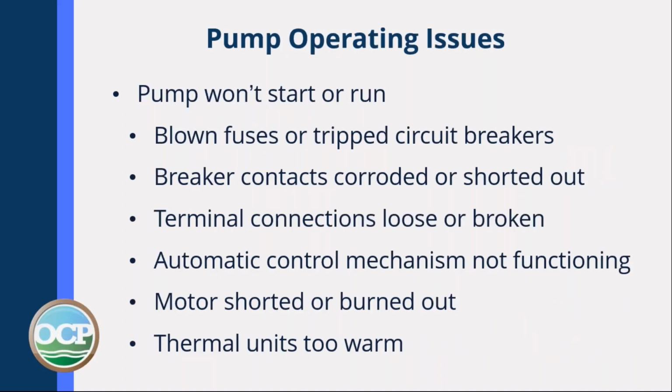Operating issues: if the pump won't start or run, check for blown fuses or tripped circuit breakers, breaker contacts that are corroded or shorted out, terminal connections that are loose or broken. Check the automatic control mechanism, and see if it's functioning or not. Make sure it's set properly.